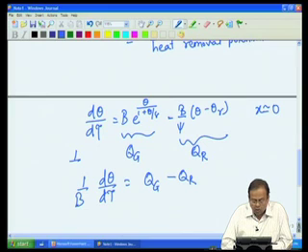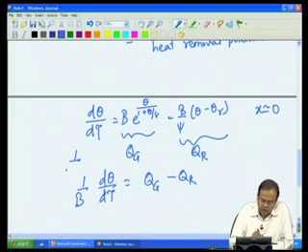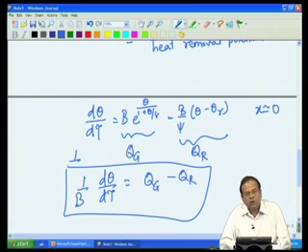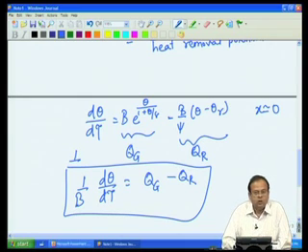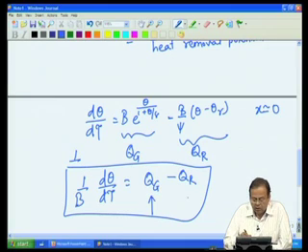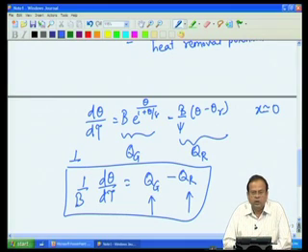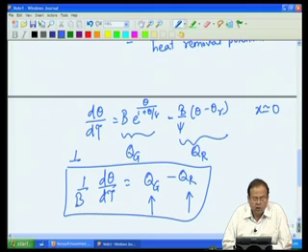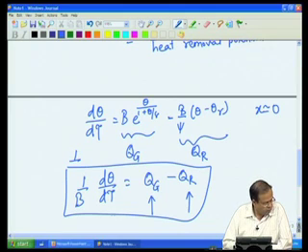Okay. So, what is this energy balance trying to tell us? It is trying to tell us what we expect actually, that change in temperature along the length of the reactor will be a result of imbalance between the heat generation and heat removal. That is what we expect. So, if heat generation is more than heat removal, we can expect increase in temperature. If heat generation is less than heat removal, we can expect the lowering of temperatures along the length of the reaction.